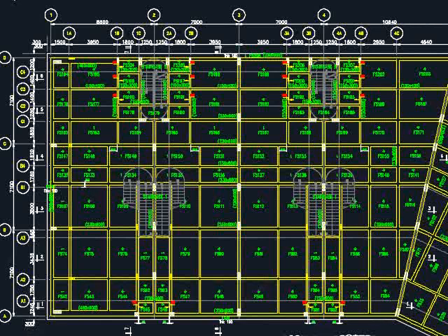Normally, you start the detailing of the slab with the structural key plan. When you need to produce the detailing, you first need to establish the structural key plan. Make sure the structural key plan is properly produced, and then you decide the sections that you would like to cut to be demonstrated to the contractors.